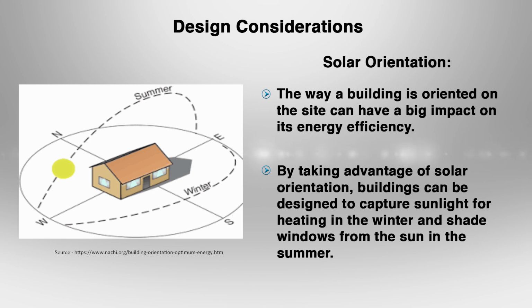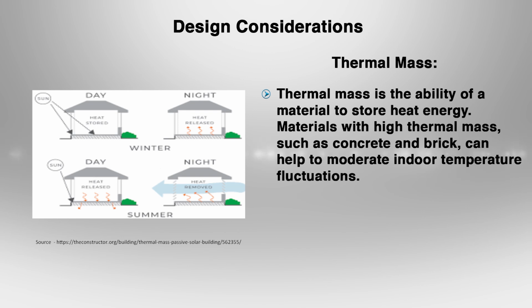Temperate climates require a balance between allowing solar heat gain in winter for passive heating and providing shading to prevent excessive heat gain in summer. Optimizing natural daylighting and ventilation are also important considerations. For cold and snowy climates, prioritizing highly insulated walls, minimizing thermal bridging, points where heat can escape, and designing the roof to handle snow loads are crucial aspects of building envelope design. Now, in the next slide we will discuss the role of the building envelope in energy efficiency.